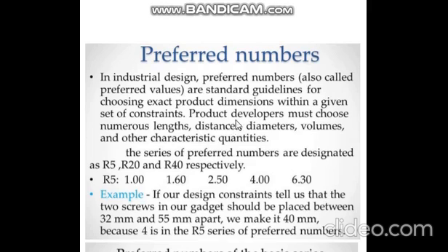The product developers have to choose numerous types of lengths, distances, diameters, volumes, and numerous other quantities. So for selecting these, a series of preferred numbers are designated. These preferred numbers are designated as R5, R10, R20, R40, like this.